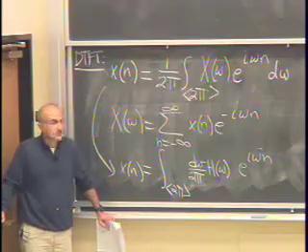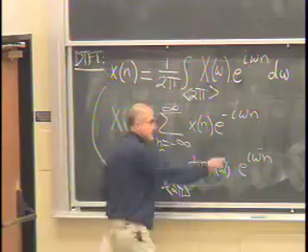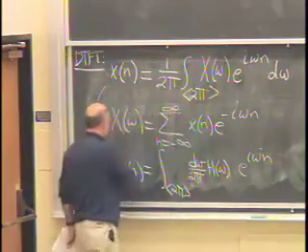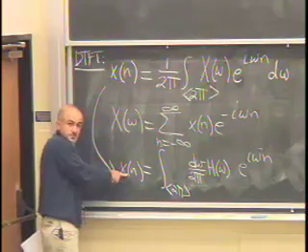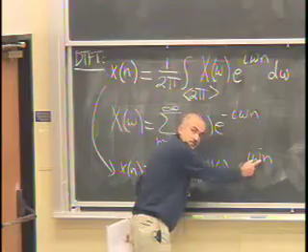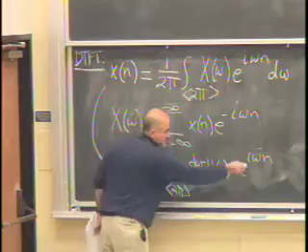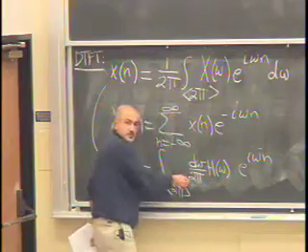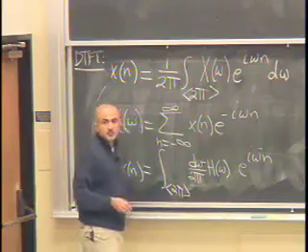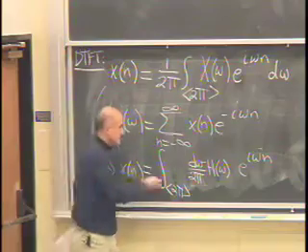That's what this is. And it's a generalization of what you learned in Fourier series. In Fourier series, these frequencies formed a discrete set. You could count them. But for an arbitrary signal, x, which may not be periodic, there is a continuum of frequencies that are present in the signal. How much of each is present? Well, according to this. But what's common among all the frequencies is the d omega and the 2 pi. It appears for all frequencies.